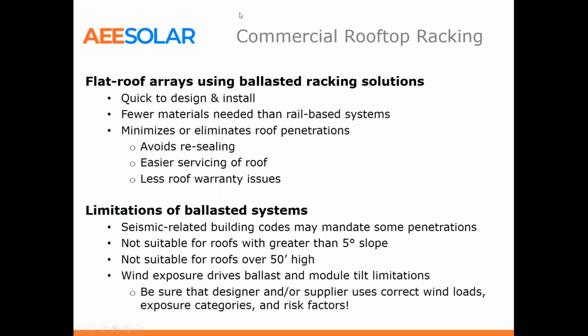Okay, so moving on to commercial rooftop racking, flat roof arrays. We're seeing many customers, and I'm doing many designs each week, for ballasted racking solutions. Ballasted racking is pretty quick and easy to design and install. You can look at some sample installation videos if you Google Aerocompact on YouTube, showing how quick and easy it is to set these up. Much fewer materials are needed than with rail-based systems. Typically, whole projects can be shipped out on a pallet or two. No long rails, and you don't have a lot of roof penetrations and mounts.